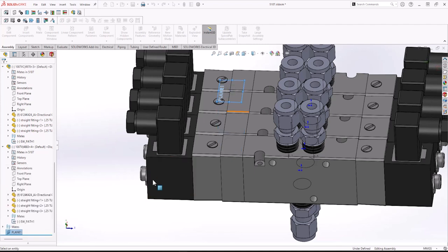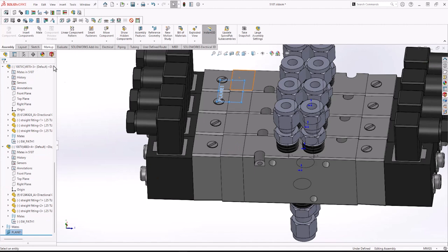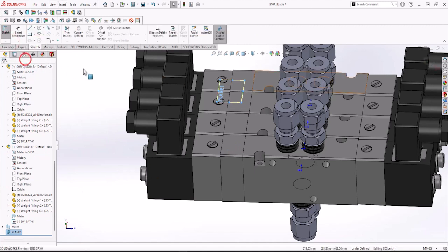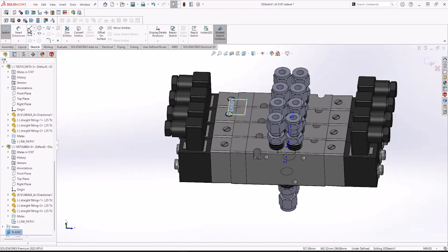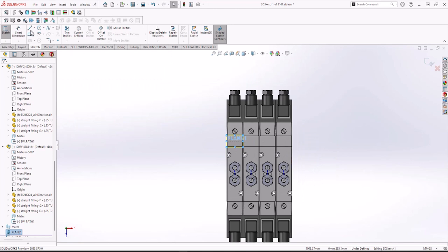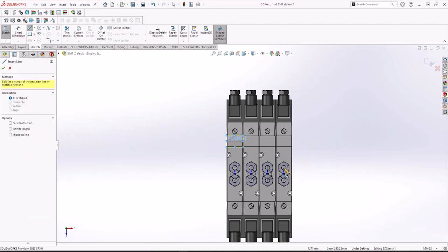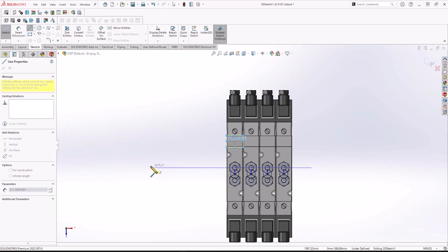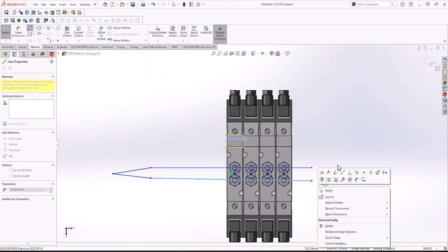So we'll go ahead and make a reference plane, and then we will put a sketch on a 3D plane. I like using these 3D plane sketches because then it becomes very easy to adjust or modify if it is required for repositioning, moving up and down without blowing up your sketch.